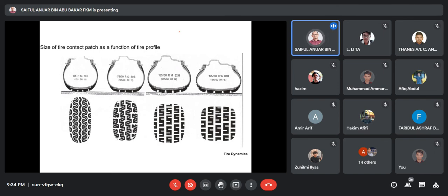So what is aquaplaning? Aquaplaning is when your wheels step into a pothole filled with water, and at that moment there is no contact between your tire surface and the ground. Even though this condition happens instantaneously, it is very dangerous because once your tire loses contact with the ground, you have a tendency to skid, which can cause an accident.